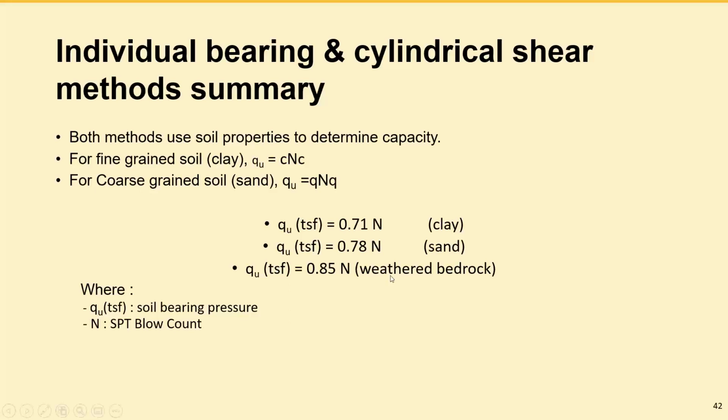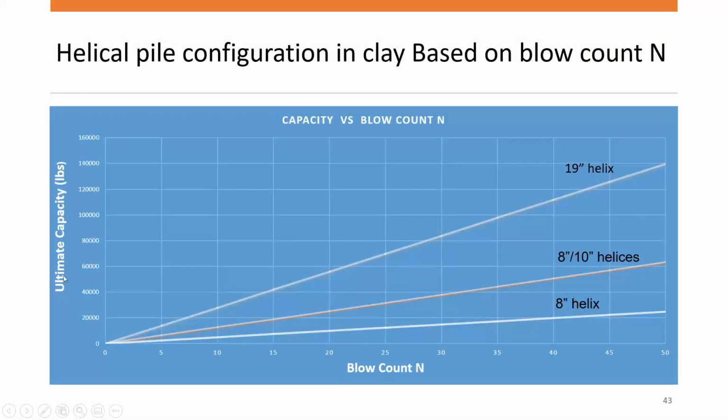As a matter of fact, that's what I'm still using. I'm going to show you how you can use this. Okay, this is the ultimate pile capacity, this is the blow count N, and this is the helix configuration. You can use this as a preliminary analysis.